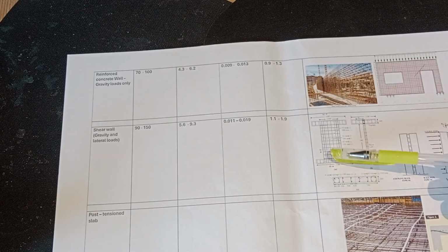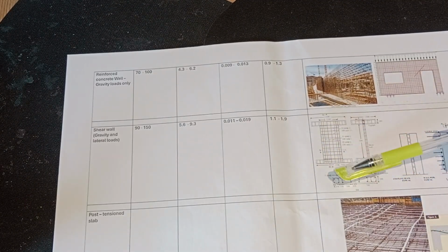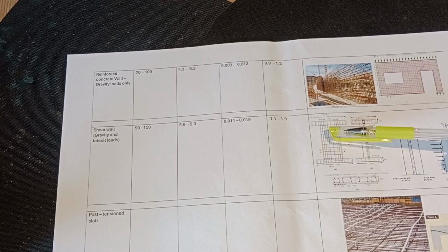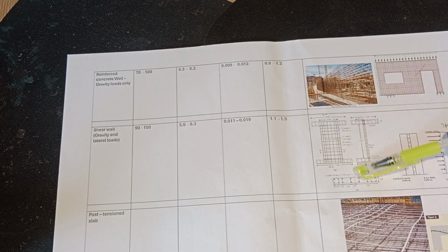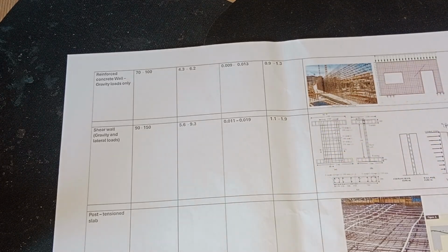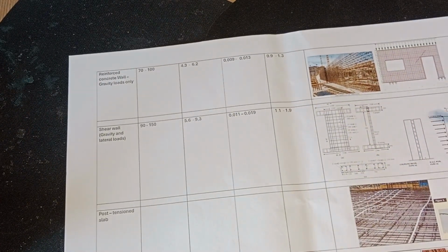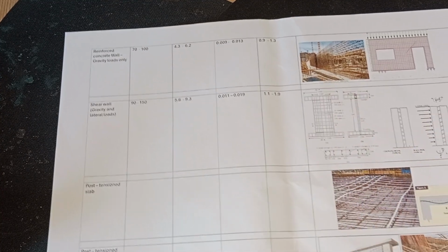You see here, in shear walls in general we have two layers and two faces, and in general at the edges we have more reinforcement, which is called the core, to have enough rigidity to connect to the other elements, top and bottom floors, and that's why the reinforcement ratio is a little bit higher. And remember, we always have ties to have efficient shear transfer as well.